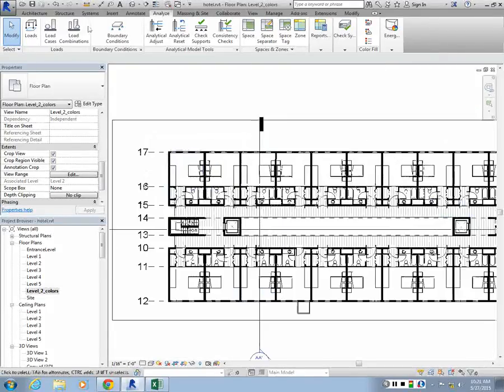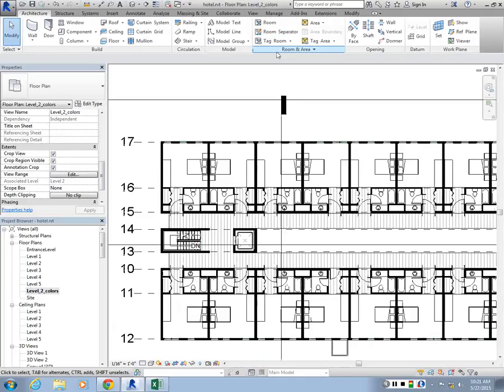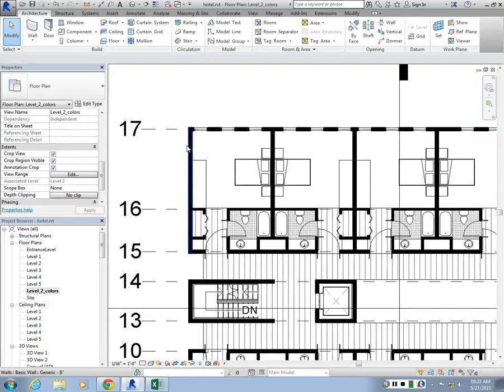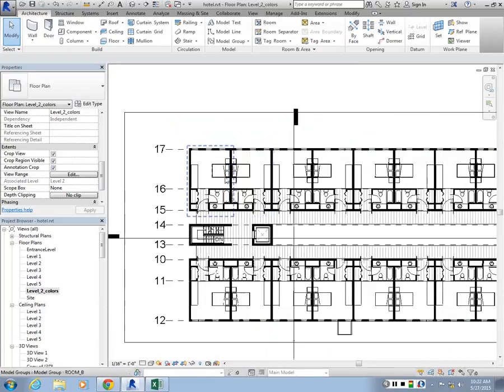Before I begin, I'm going to look at rooms quickly. So the rooms are where we associate tags to spaces or boundaries. It's located under architecture, room, and area. So you have to do these individually, unfortunately. You have to define each room space individually, but you could do it as a legend, like to one unit. And for the floor plan, you could just have like an overall one tag for the whole room or space.